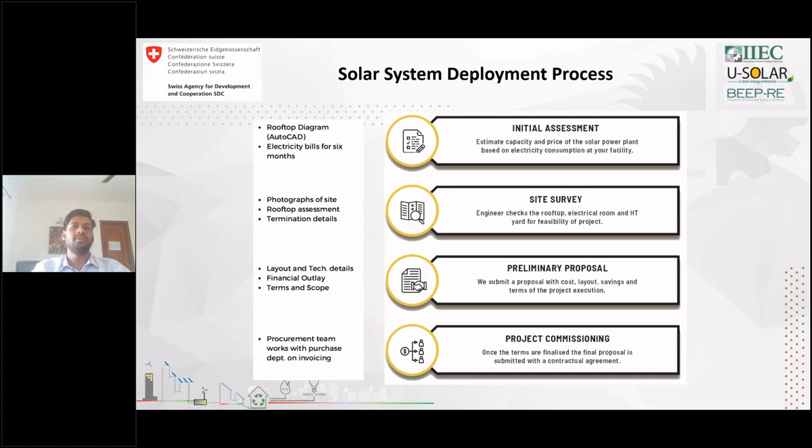The electricity bill basically gives an idea of load consumption for a particular industry or a residential space, wherever the application may be. So what you need to look out for in an electricity bill is a section called sanction load. Sanction load is something which we apply for from the distribution company.